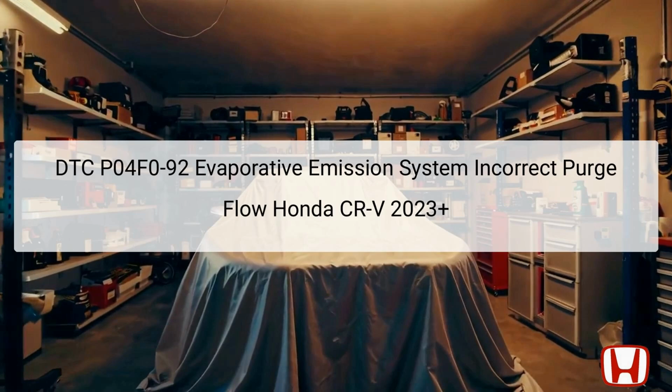The diagnostic trouble code DTC P04F0-92, also referred to as Evaporative Emission EVAP system incorrect purge flow detected, indicates an issue with the vehicle's EVAP system. This issue is registered when the Powertrain Control Module, PCM, detects that the purge flow is not operating within specified parameters during pressure checks in the boost side of the system.